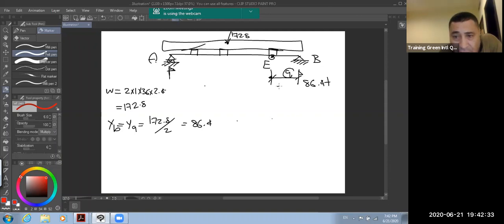Giving moment in this direction. See the arrow. Watch it. Where is the tension? Giving tension in the lower fiber of the beam AB. I'm not talking about this block; this block is the load, dead load, resting on 3 particular supports on the beam. So the reaction at support B is giving positive moment. Why? Tension in lower fiber is always positive, because the tail of the arrow is down.